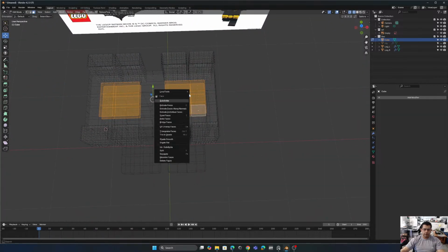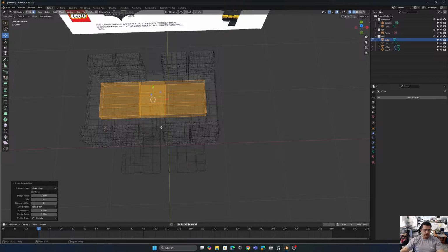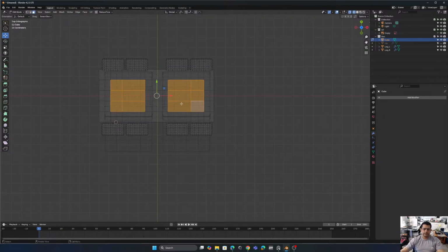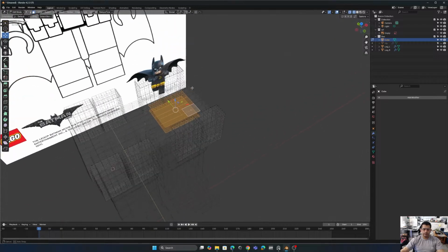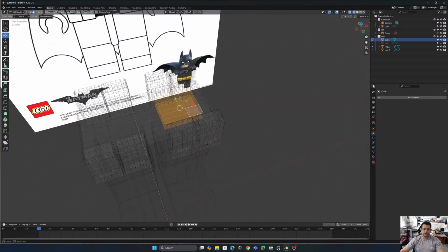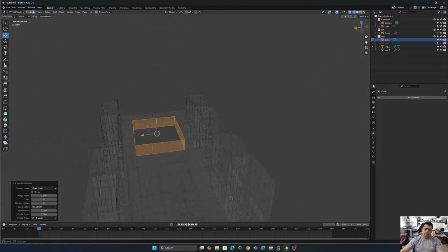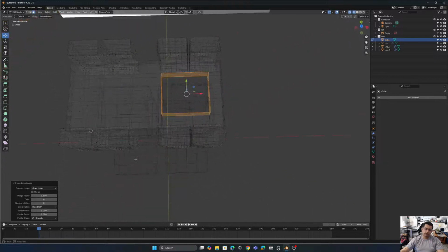And we're gonna right click and go to bridge faces. Oh, we made a mistake. So how can we do this bridge faces? You have to select only the faces that you have to bridge. That means we only could select one area, then be sure that both are selected, right click, bridge faces, and it's gonna create geometry between those faces and cap the hole.